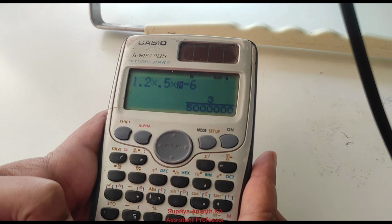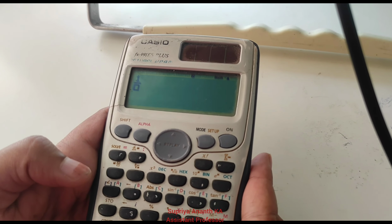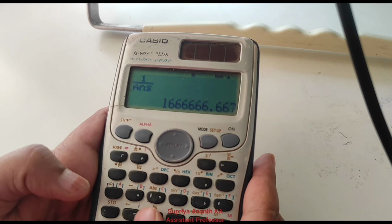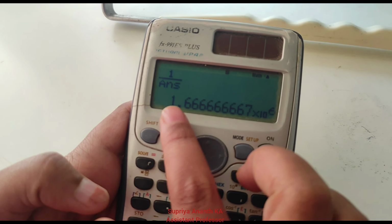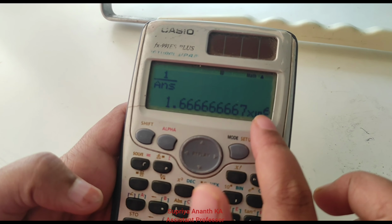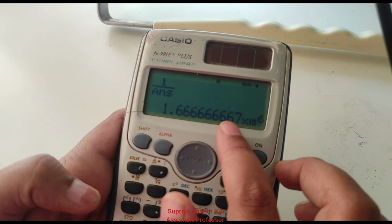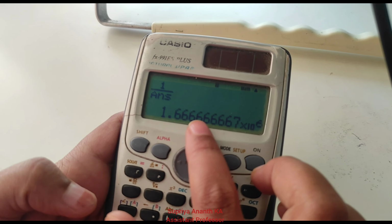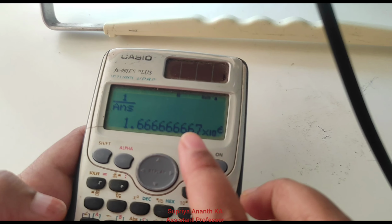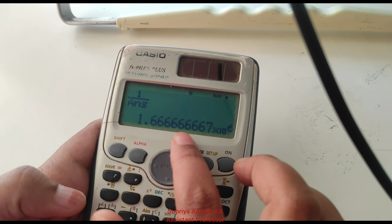The formula to calculate the frequency is 1 divided by T. I am going to substitute the same. Here you can observe the value we are getting is 1.6 megahertz. The theoretical value for the crystal is 2 megahertz. We have got practically 1.6 megahertz due to some power fluctuation variation. You need to verify it along with the theoretical and practical value. So this is the circuit for the crystal oscillator.